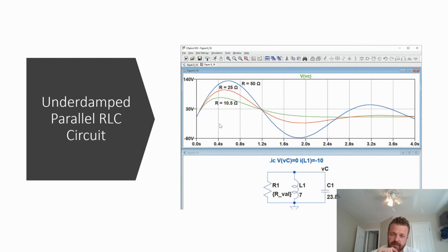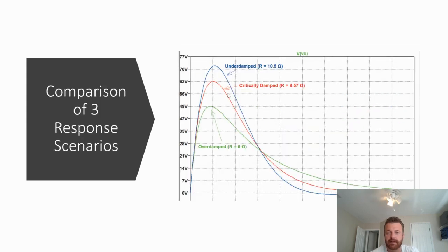But if you look at those formulas, that's not actually the way it works. As the R value increases, this thing will go from exhibiting what looks like overdamped behavior, where you have that initial upshoot and then converge towards zero and never go negative, to actually swinging fairly dramatically in a negative fashion. So this just shows you how sensitive the response of this circuit is to the actual level of underdamping that you have.